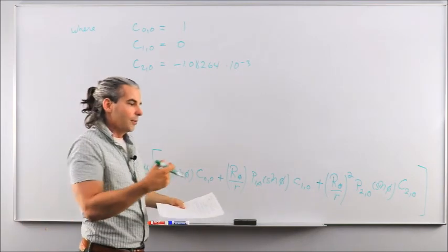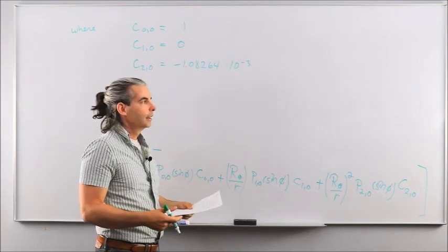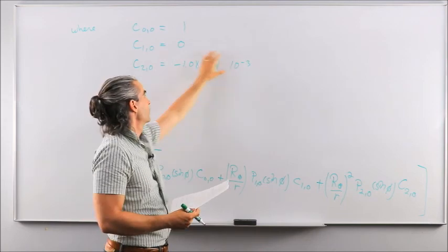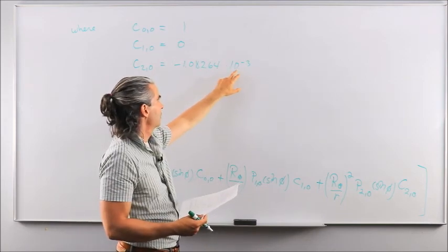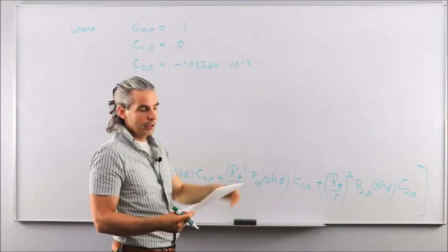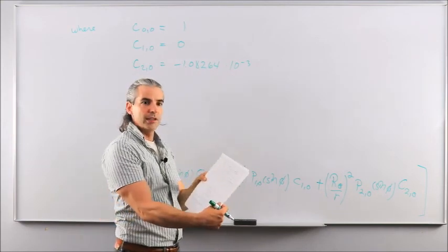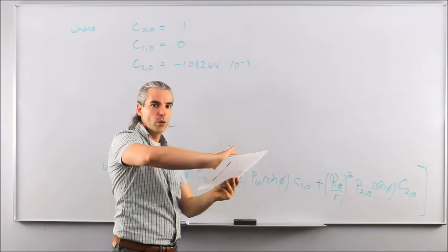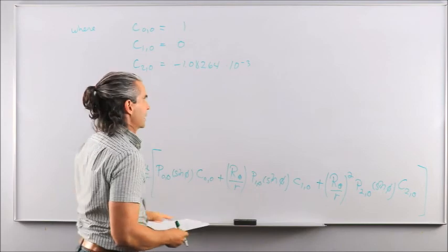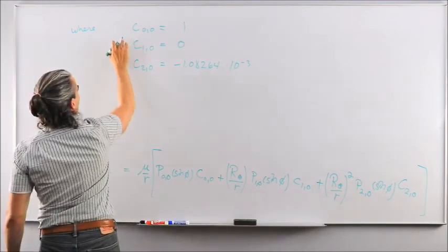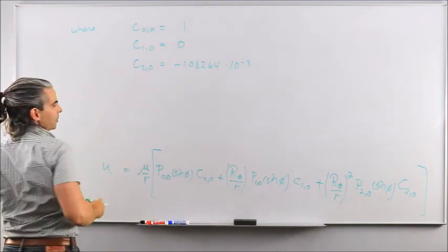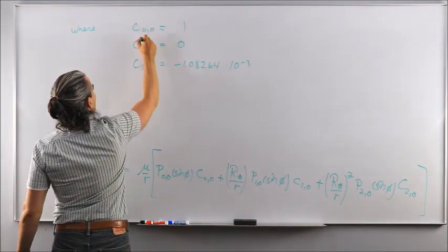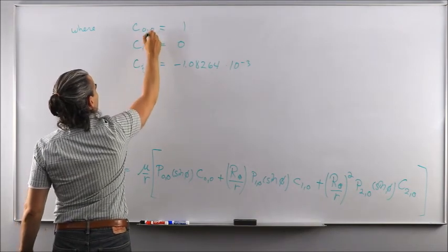So it is a small perturbing contribution, yet this is worth considering for low Earth orbit, because that will mean that only the small effect that has a power of 10 to the negative 3 is going to be able to shift our orbit slightly, or shift the orbital plane and also shift the orbit within the orbital plane. So we're going to see that later on, okay? But these are the constants for our geopotential coefficient C for degree 0, 1, 2, and order of 0, okay?